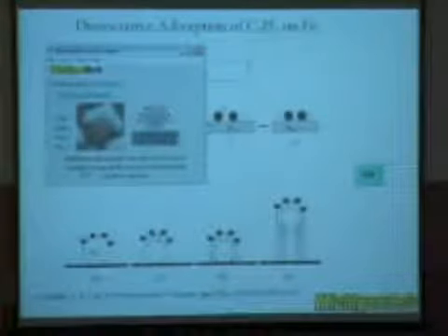Again, we put a substrate and a catalyst particle, which is iron in this case. When the C2H2 molecule starts to land on the surface, a charge transfer from the molecule to the catalyst helps it decompose very fast. All this carbon will start to absorb or dissolve inside the catalyst and start to form the carbon nanotubes.